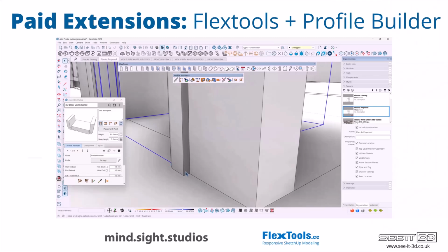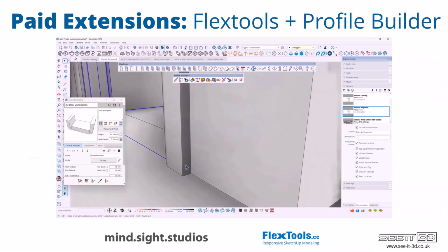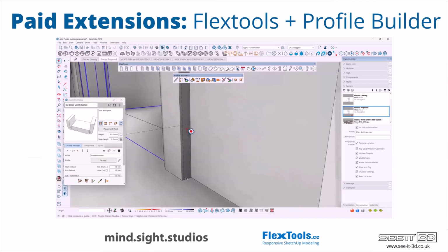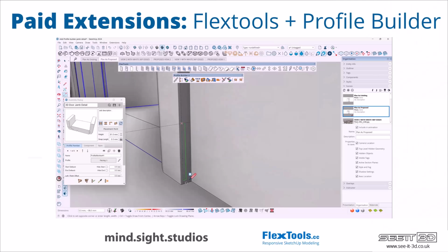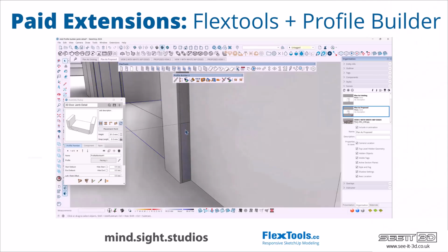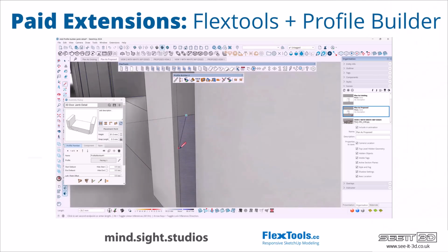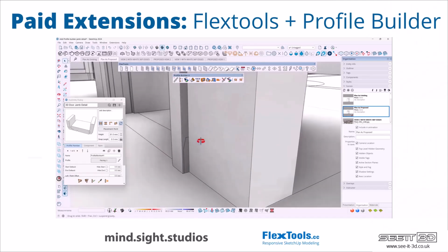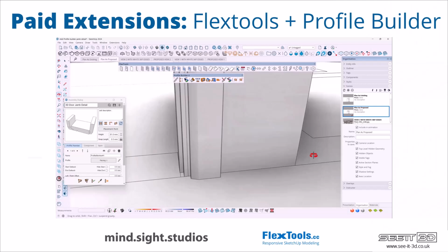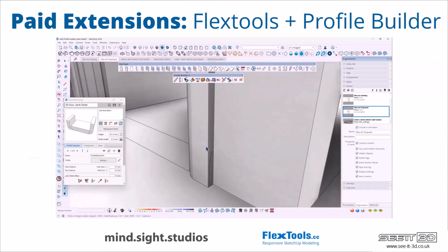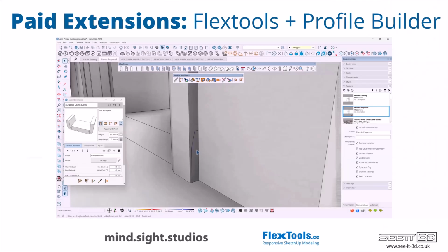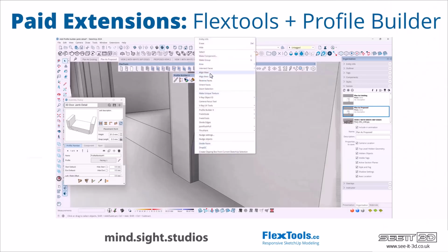fencing. So what I'm going to do here is I'm going to go to the tape tool and I'm going to tape out, let's say 15. Click from here coming up, let's say 95. And I'm going to draw a rectangle. Okay, I'm just going to go over here now, find the midpoint, and just do a very simple kind of sloping surface there, just to match in with the similar one on this architrave. I'll select it, right click, align view.